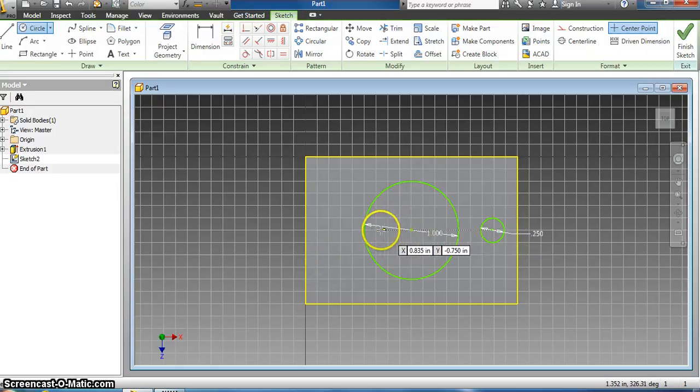And again, I'm just using this to use those guidelines so we know it's the center, dragging it from the center. Again, we'll go 0.25 here. So now we have a couple circles drawn into this. Now before I showed you just how to extrude this, and we're going to go back and extrude and cut some items out of this.